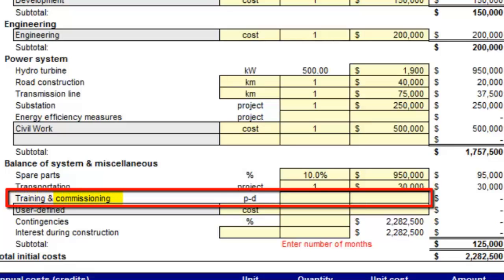Commissioning is the last activity of the construction phase. It consists of operating all of the equipment to detect and fix any malfunction and ensure that the plant functions as guaranteed. Commissioning normally involves the monitoring of the equipment performance over a set period of time under typical operating conditions.